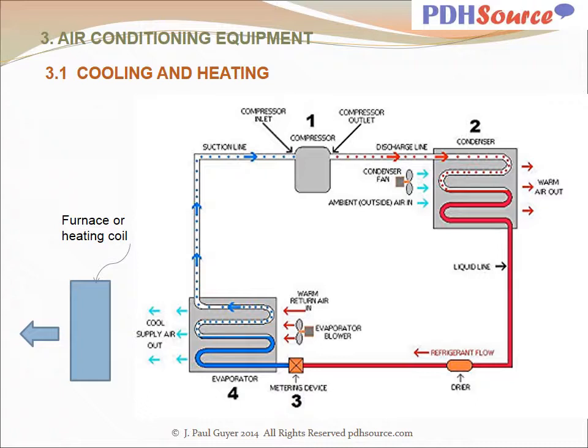And in the process of passing through this box, which is a heat exchanger, the cold return air from the occupied space in the winter is heated up and is blown by the fan back to the occupied space, where it warms up the room and the occupants, and then that air is drawn by the fan pressures back to the HVAC equipment, and again is pushed through this furnace, where the air is heated up again, and that circulation just continues.